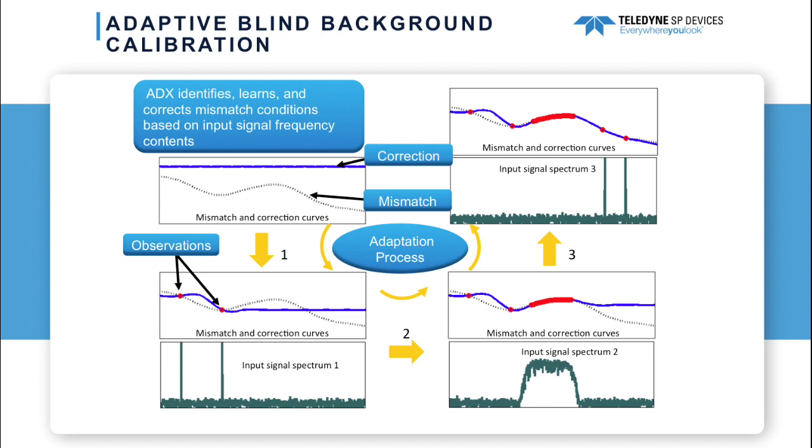The process continues and more input signals are applied to the blue mismatch model, and it approximates the accurate mismatch better and better. When the actual mismatch is changing due to, for example, temperature effects, the mismatch model will transition from modeling previous mismatch conditions to the new one. In this way, the mismatch model will track the actual mismatch conditions in a smooth way.